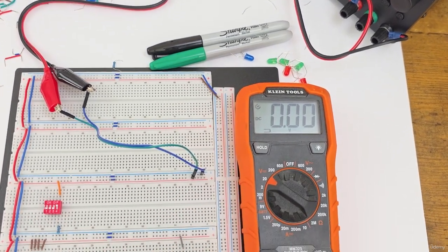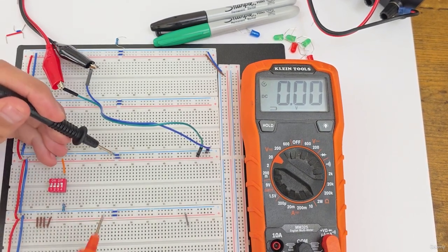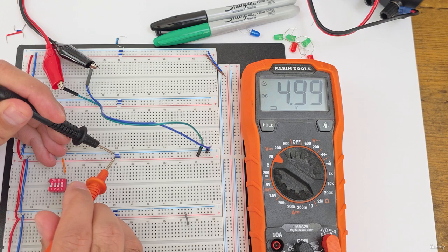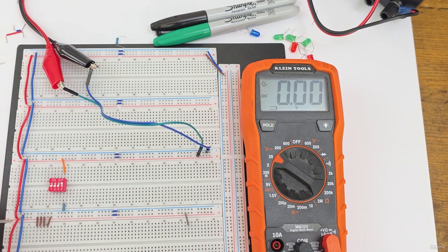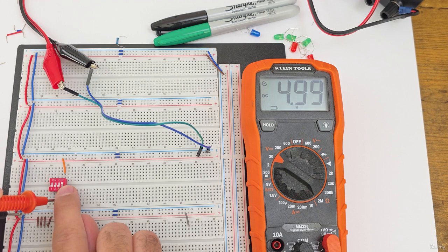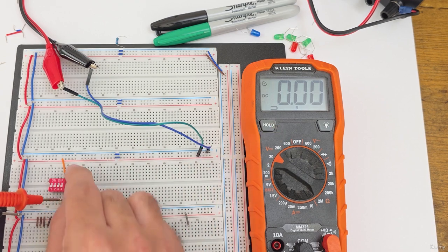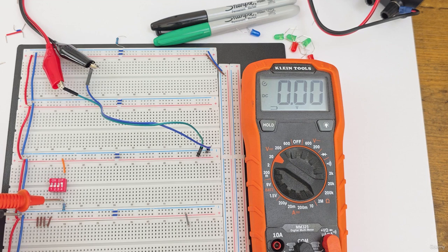The first thing that I'm going to do is measuring the power supply. Do you see? It is almost 5 volts. And then let's connect this to the ground and measure here. You can see that it is 5 volts. That is because the switch is on. When we click this here, you can find that the switch is off and it is providing 0 volt. Again, click on this. It should be 5 volts.